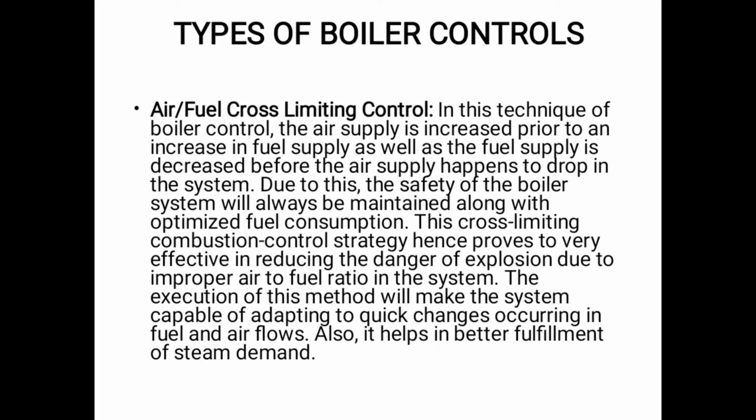This is the most advanced control system to reduce the risk of explosion in the boiler. It means that when the load becomes high, the air increases first, then the fuel increases.